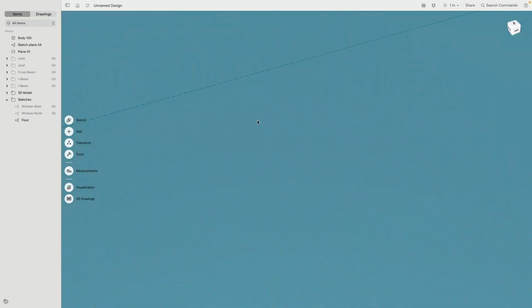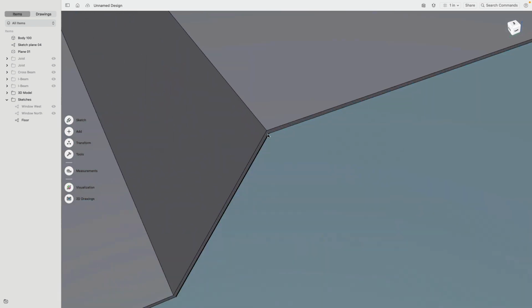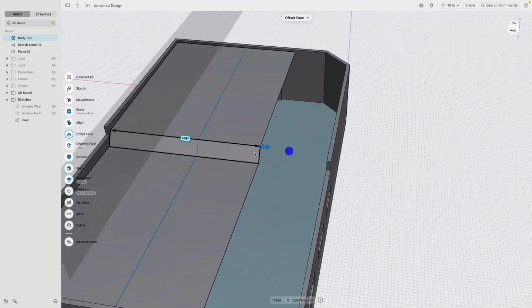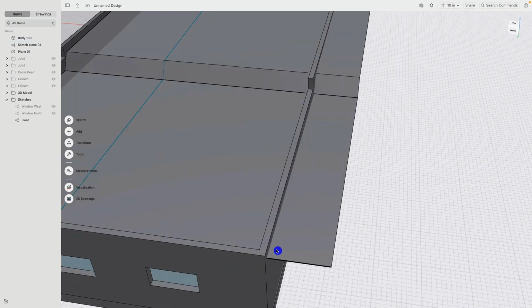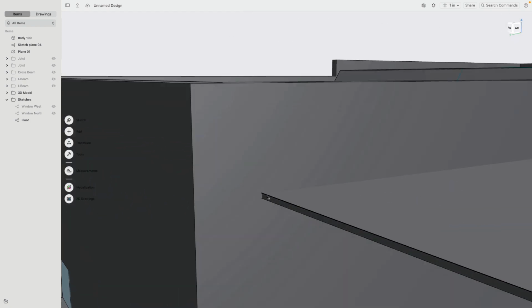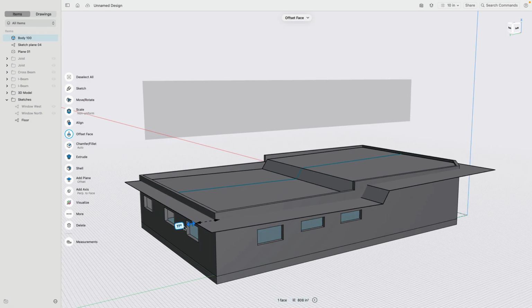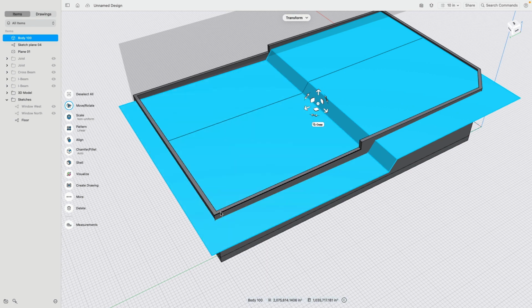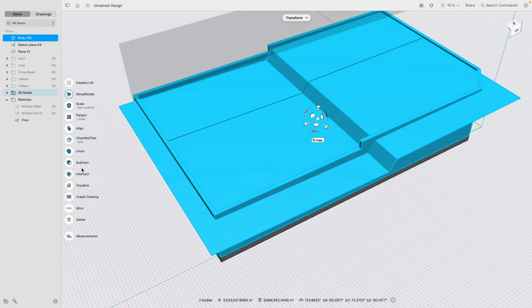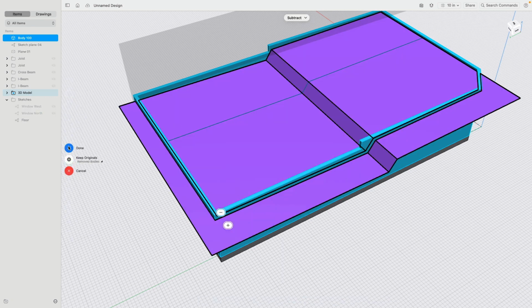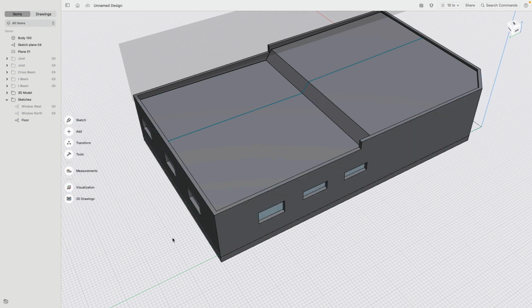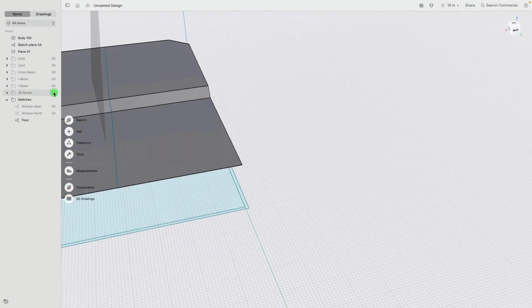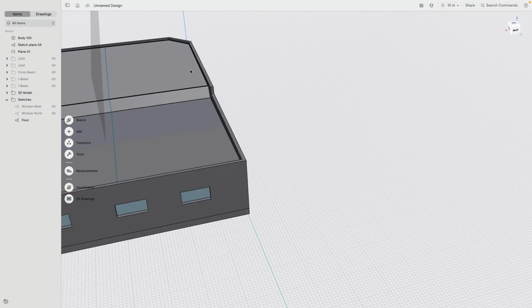Yeah, it's okay. There are always many roads that lead to Rome. So this tiny thing, you know what? Here, I extrude over. Can also simply do it this way and then select this one, move this over. Very good. And so what I will do now is I will select the roof. I would like it to be cut by the wall. Subtract, keep remove bodies, and then here, this is the outside piece I can take off. And there you see it, perfectly trimmed.